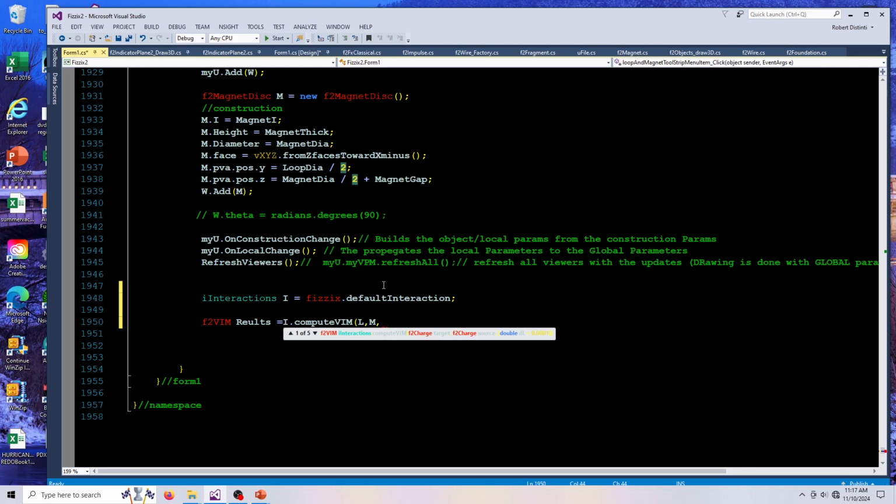And then here is where you add the fragmentation length. I'm sorry for my poor choice of colors here. You can't see this. This little value here is the default value. If you don't enter anything, it is 1/10 of a millimeter, which is fine for most purposes. Alternately, you can specify your own fragmentation length if you want. This is the length for the finite element analysis. Again, we're going to explain the difference between fragmentation length, segmentation length, and filament length, and how all those interact, a little bit later.